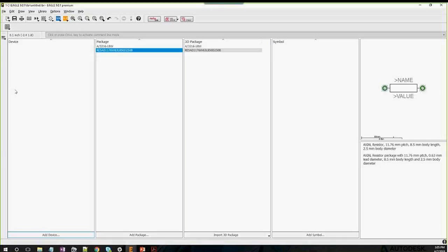For the slots, if you're making slots, then you have to draw those on the milling layer and export those as their own Gerber. Again, these are workarounds that we have right now, and we do plan to address those needs in a more formal way in the near future. So for Amaldev, hopefully I didn't mispronounce your name, that's the answer to your question. Right now, you have to use the arbitrary pad shape functionality if you need any arbitrary shape, and you have to use slots drawn on the mill layer to be able to make slotted drills.